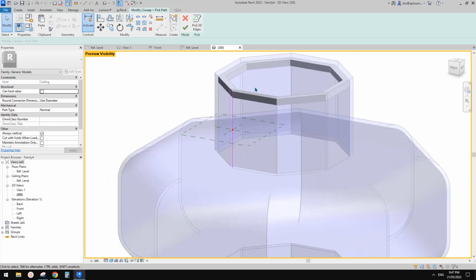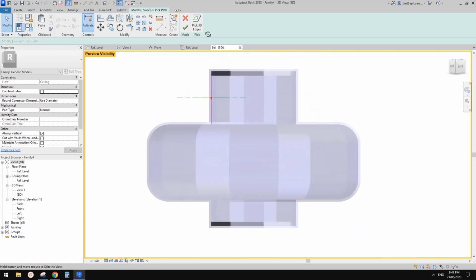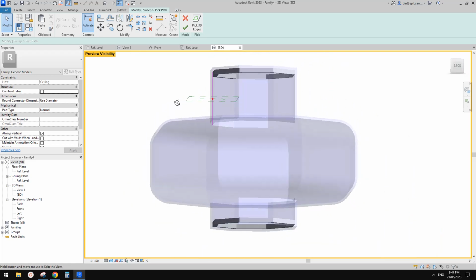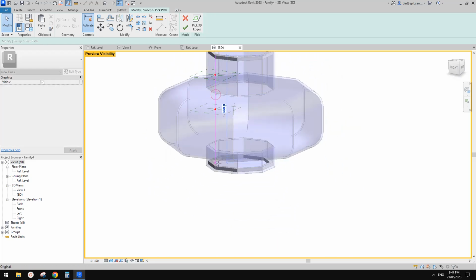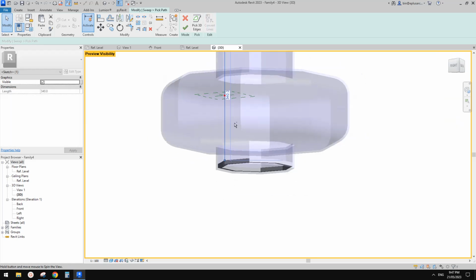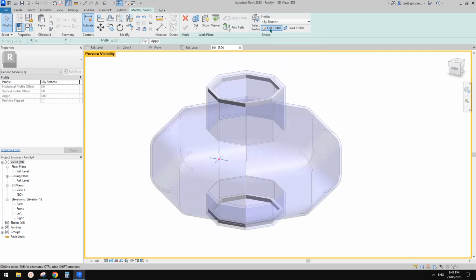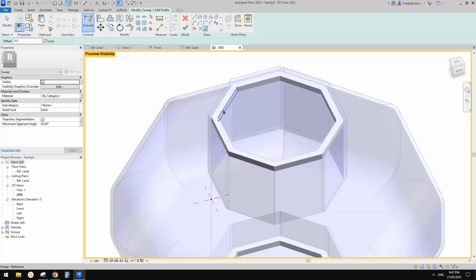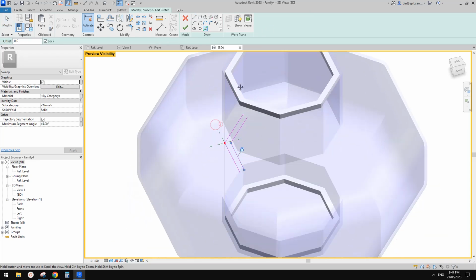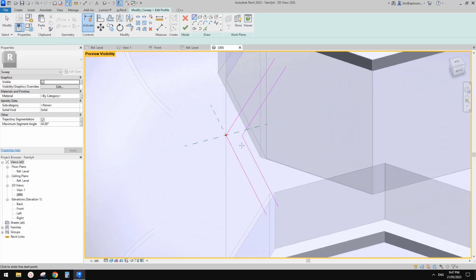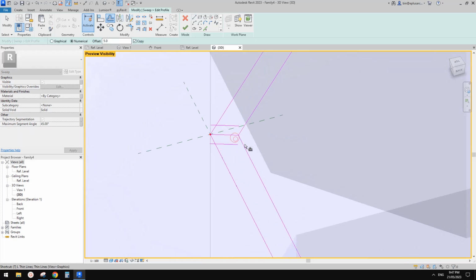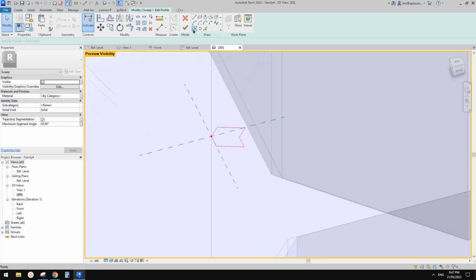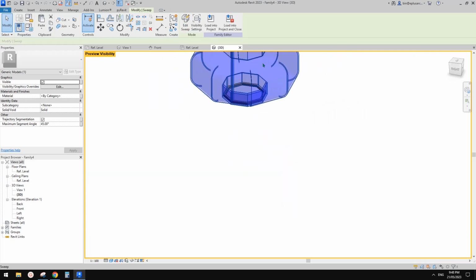Okay, and then oh, hang on, it's not going all the way to the bottom, so we can drag this down. Okay, let's drag this down to here. Okay, so finish, and then we need to create a profile. For the profile, we are going to just pick some edge on this frame, and then maybe I'll just conduct this offset OF, maybe 5 on each side, then just trim them, delete the middle one, finish. So now we have a vertical.